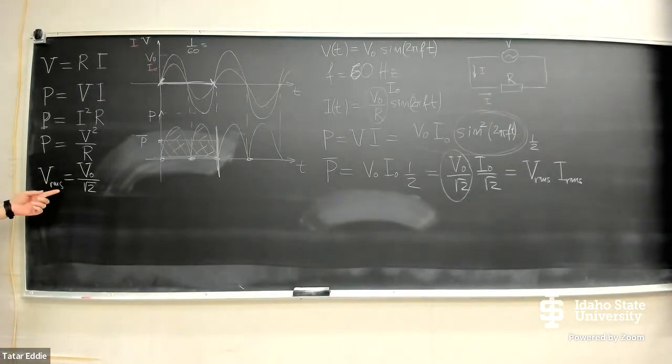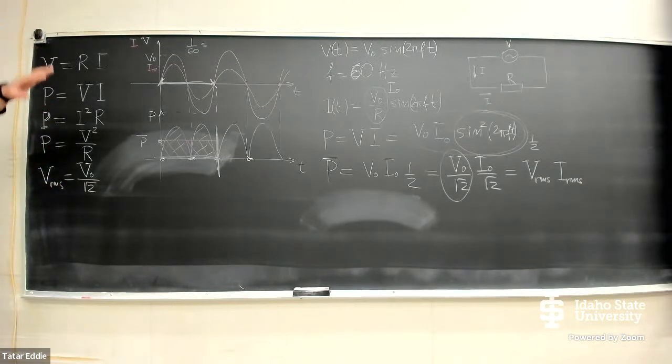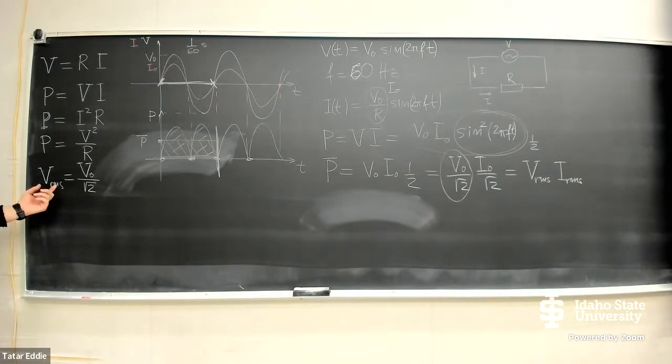And well, RMS stands for square. So square it. After that, take the average, take the mean. And to compensate for the fact that you have squared it, take the square root. And this is how the expression root mean squared comes out. You squared, you found the mean, and after that, you took the square root. This is the idea behind the process.